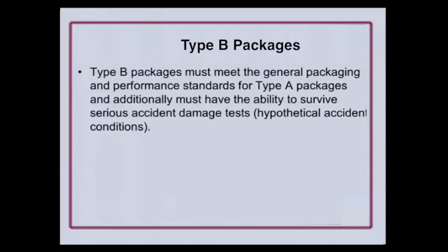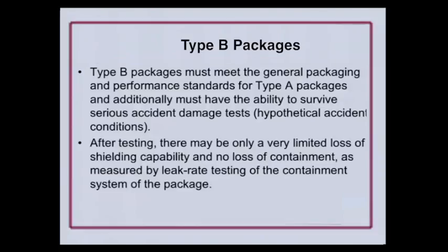It also has to survive a hypothetical accident condition, severe accidents. And in doing that, it has to undergo these specific tests. Also, after testing, there needs to be no or very limited loss of shielding capability, no loss of containment, and that is verified by leak rate testing of the containment afterwards, after the testing is done.